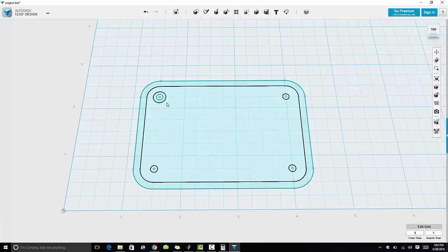For those of you who know a lot about 3D printing, you know exactly what I'm talking about when I'm talking about bonding. For those of you who don't, layers. 3D printing is basically consumer grade 3D printing, I should say. There are a couple different types of printing methods, but the most common one is fused deposition printing. That basically means you have some filament that goes into a tube or a heating chamber, it heats it up, and then there's an extruder at the bottom that extrudes the plastic, and a motherboard or some kind of controller tells the head where to go on the board.